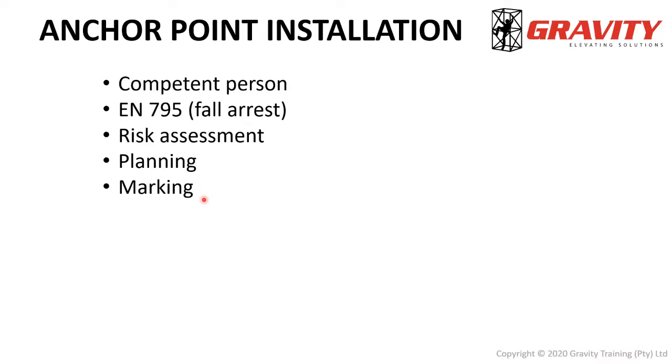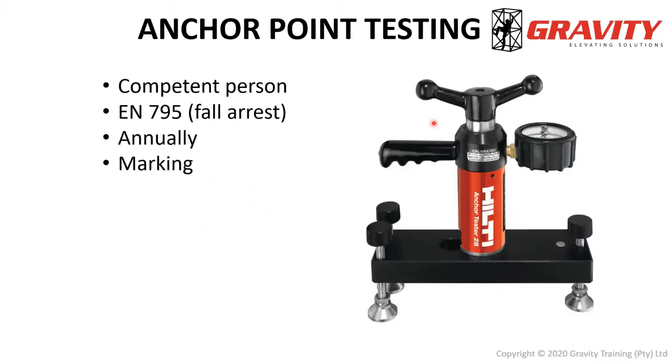And then of course, make sure that all your installed anchor points are marked, specifying the limitations of that anchor point and the standard that they have been installed to, as well as who they were installed by, so that you can follow up and hold somebody responsible if that marking is insufficient or needs updating, whatever the case may be.